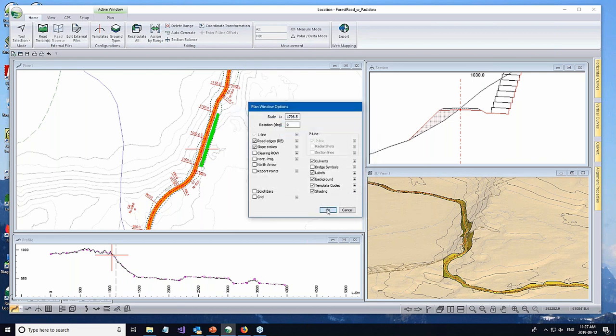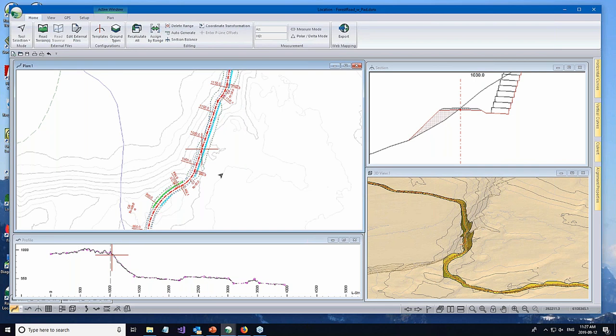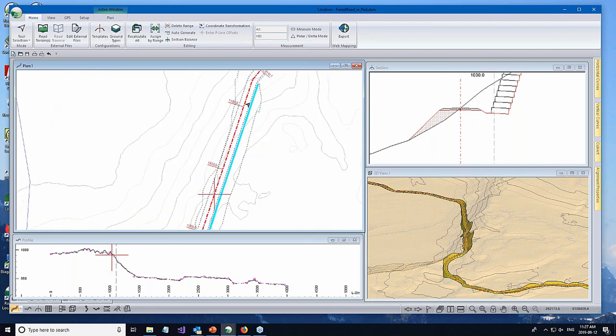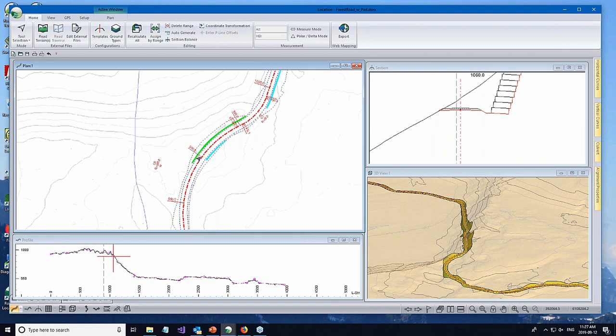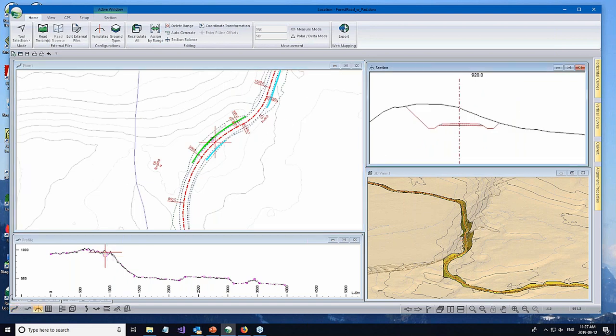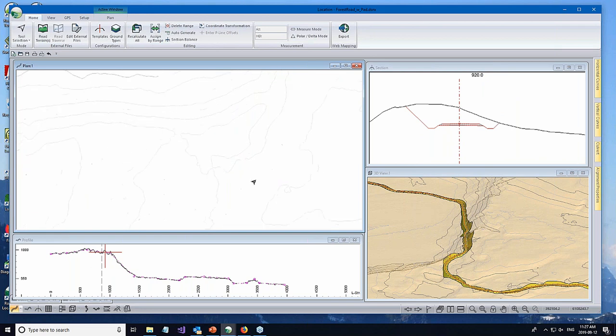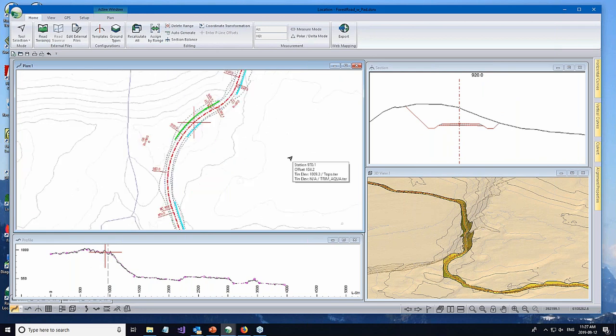And we'll just go ahead and shade that. Now, if I zoom into my area, you can see in a section here, we've got a bit of a ditch showing. And a section down here is going to have ditches on both sides, and so on. Again, you can export it, get the areas, or just use it to visualize things.